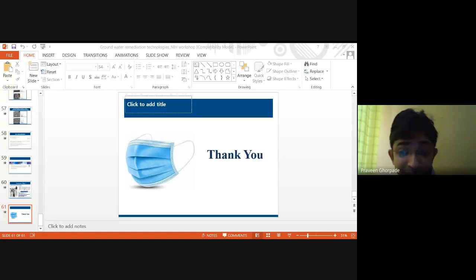Now, this is a real challenge from industry. They want us to tell them to what level they can blend the red mud. Blend in the sense at the manufacturing end, when you push red mud in at the feed end of the kiln, when the raw material is going inside the kiln, what is going to happen? They want us to know the phase transformations, whether the four phases in the cement, alite, belite, aluminate, and ferrite, are going to get affected, or whether strength will get affected. Ultimately the cement has to be marketed. Tomorrow, if you put something in it and it affects the cement quality adversely, then it is not going to help.